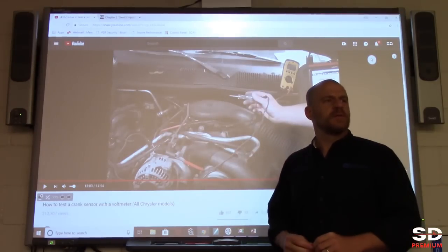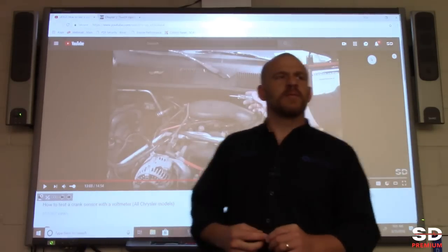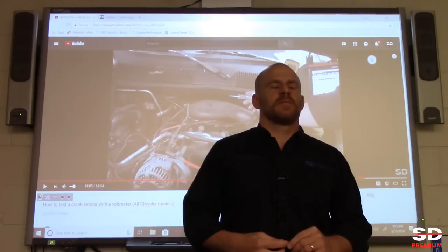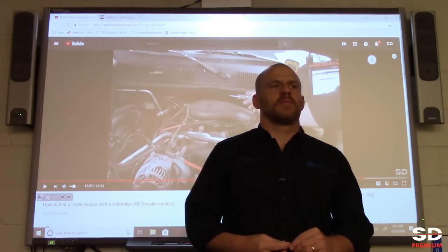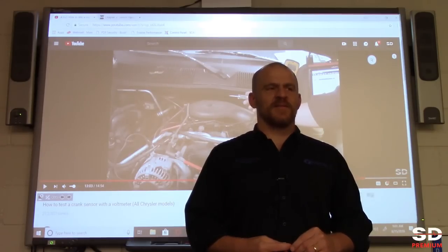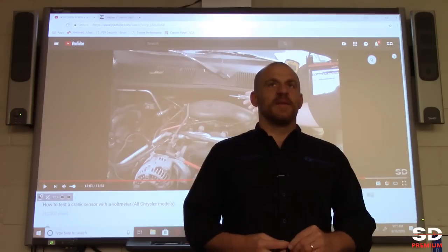I was just kind of curious, so you say even if certain things can't be set, the data PID will still show, like say you try to command the AC compressor to engage. Yes. And if the AC compressor is not working, you'll still see a PID saying the command to be on. Correct. Okay. Yeah, and that's a little bit different.